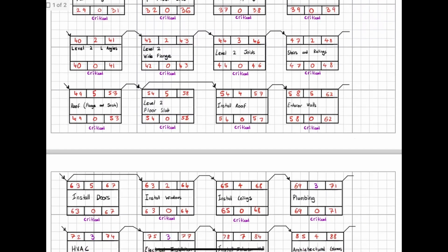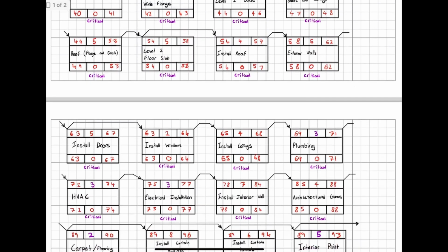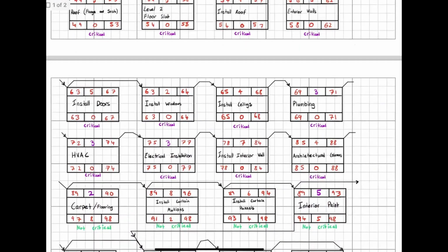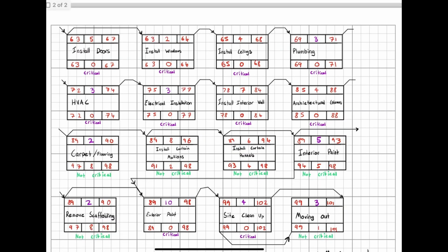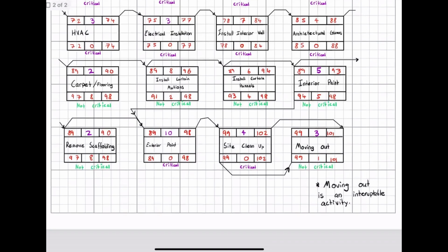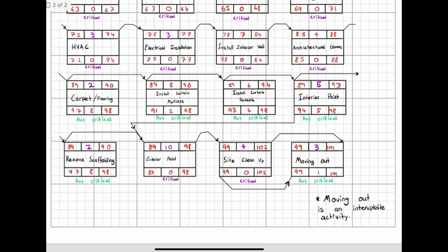the different projects. Once this was completed, the activity durations were imported into BIM, where they were run in the timeliner function to visually verify if they were in the correct order. Once some tweaks were made, the critical path was able to be decided, and we could proceed with the project.